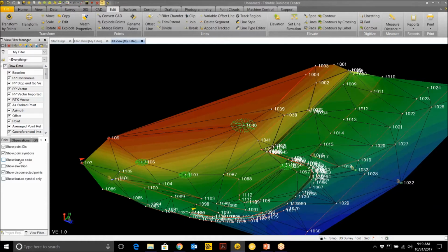I also did have another question before we move on. All your line work, when it comes in, that line work is at its actual elevation based on the point, correct? So it is three-dimensional line work? Correct. Yes. Right now, everything right here is a polyline. It's a 3D polyline. Everything that you shoot in there, as soon as it comes out of a line, it's a 3D polyline. So when it's going in, you're in the 3D world.